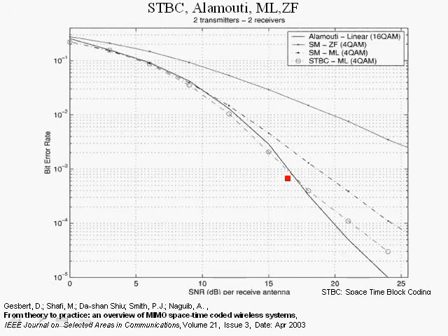So the actual throughput of the Alamouti scheme with 16 QAM is equal to the 2x2 MIMO maximum likelihood system with 2 spatial streams each at 4 QAM. So the bit rates are the same, yet we see that the Alamouti scheme has a much better performance than the spatially multiplexing 2x2 MIMO system using maximum likelihood.